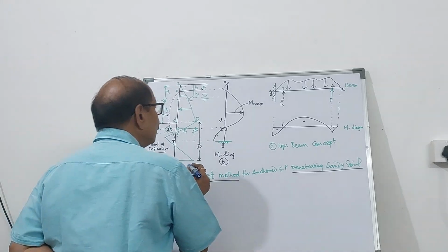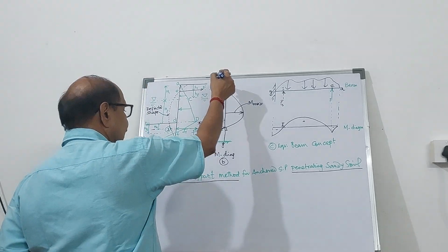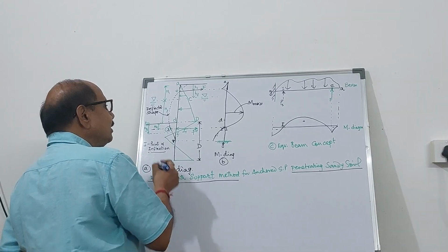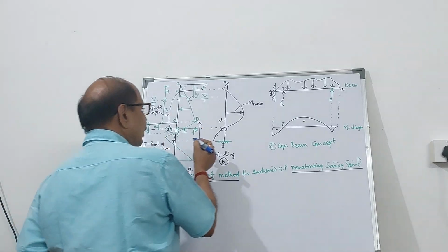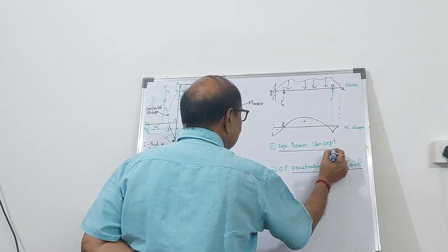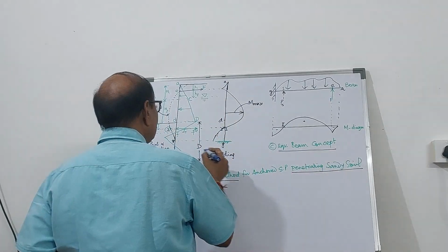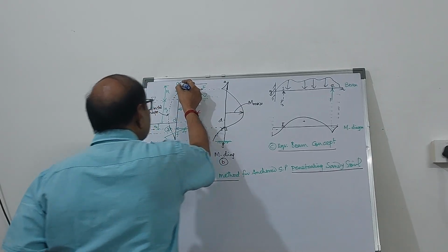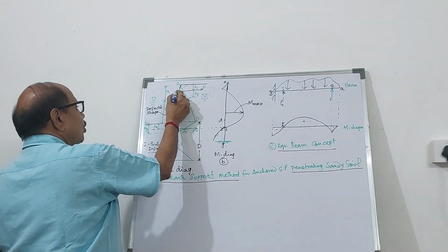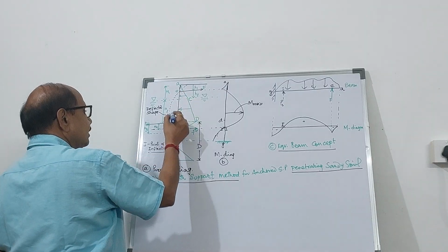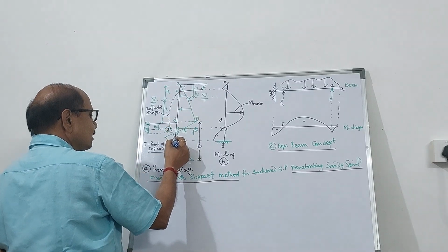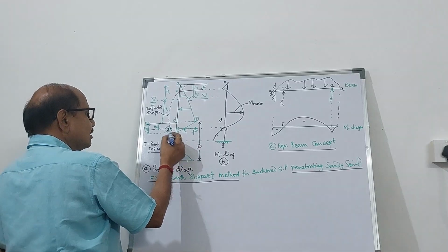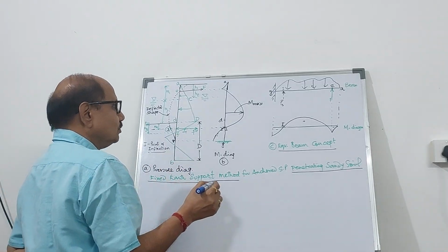And if you want to draw the bending moment diagram, then what you can do is consider the equivalent beam concept. So here, from G to A, the top point is A, the anchor rod is provided at E, D is the dredge line, and G is the point where there is zero deflection.